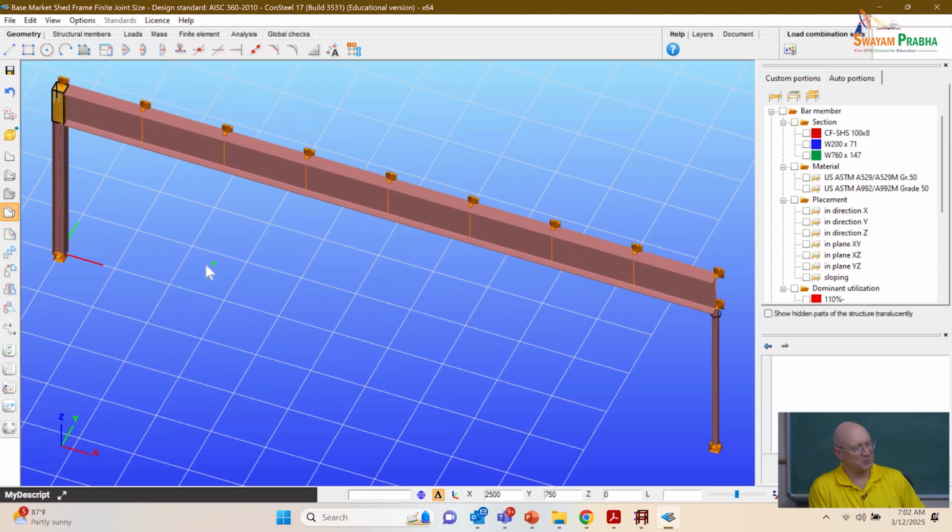A few subtle things with that. The pin was basically at the location of the reference axis or centroidal axis of the roof girder in what we modeled in the analysis model I showed you yesterday, which is a typical approximation that we often would use in engineering design.